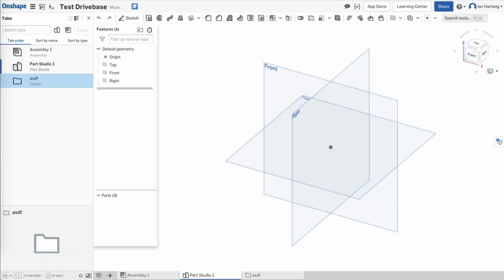I'm going to jump back to our new document, and here we're presented with blank 3D space. There are some blue things here, but these are all basically just empty reference planes. So to get started, we need to define a sketch, and you have to put a sketch onto a plane that already exists. Once you create more geometry, you could use an actual face of a part. But since everything's blank right now, let's just pick the top plane.